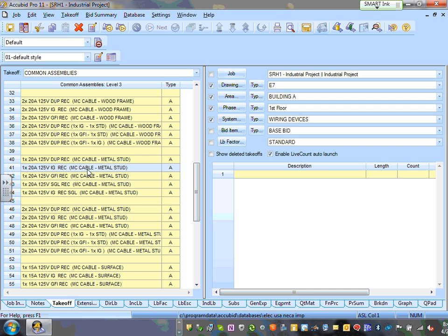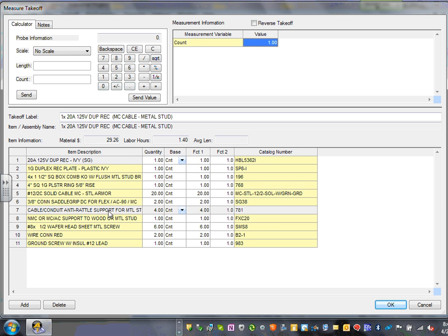The one underneath it is with isolated ground. We're not asking for isolated ground, but you can do it. Can everybody see that one? Click on that one. And here's what comes with it, guys. The most important thing is the 20 feet, the 20 foot. Can I get your attention here? Derek, when you take the receptacle, you do not loop them anymore if you use that one, because it comes with 20 feet of MC cable.